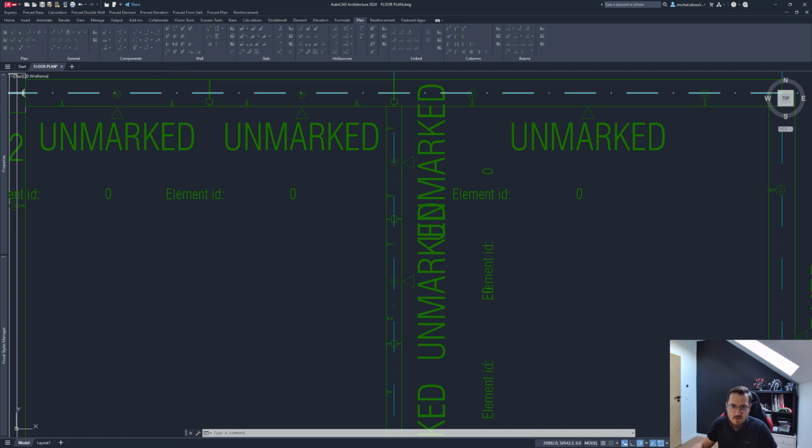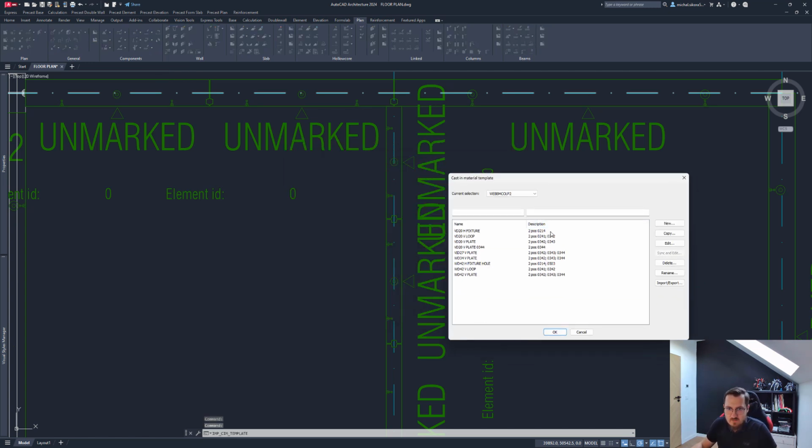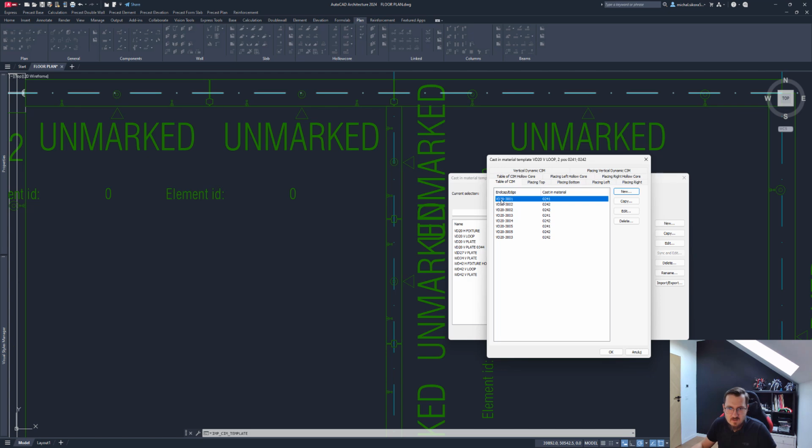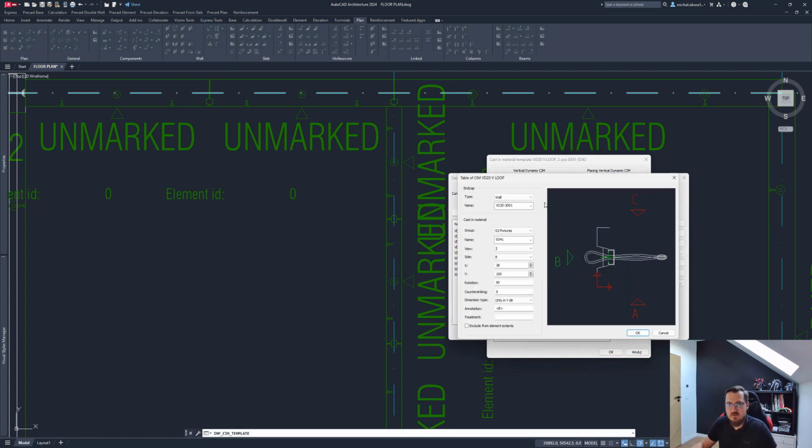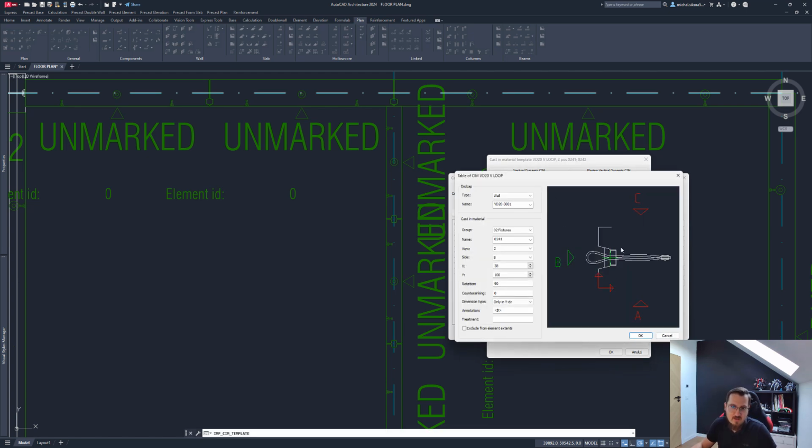Custom material templates, again, quick explanation. The type of wall I have here is for my 20 size wall. It will look for this particular end cap, which I just applied as I split this wall. I'll open that and edit, and I will apply this particular casting material at this end cap, at this location, which is that green cross. I can of course move that, say 50, and it moves inwards. 38 is sufficient, so it looks very nice. I can rotate that, move it further out. I can also change the angle to 45 degrees if we have some kind of connection like this. Well, let's leave it at 90.